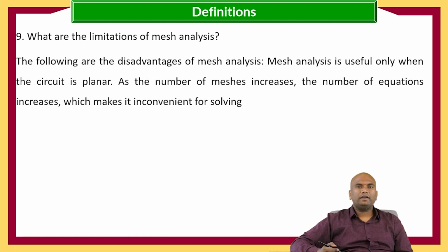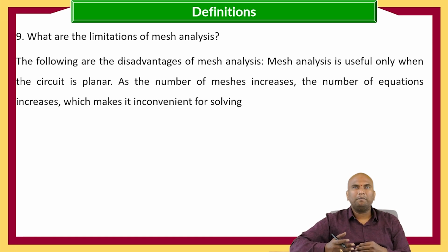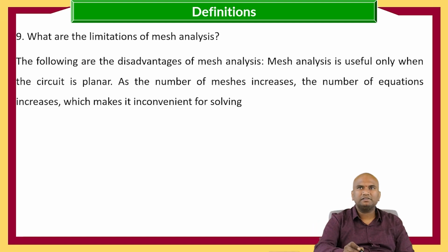Now, what are the limitations of mesh analysis? For mesh analysis we have to apply KVL. So in order to apply KVL, the circuit must be planar, and as the number of meshes increases, the number of equations will increase, which makes it inconvenient for solving.